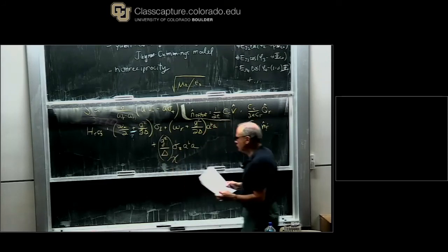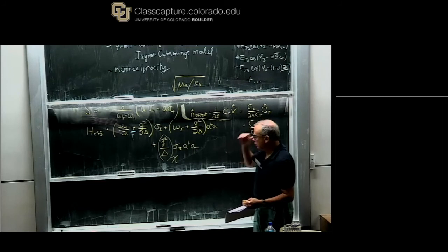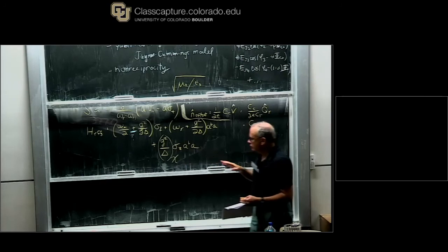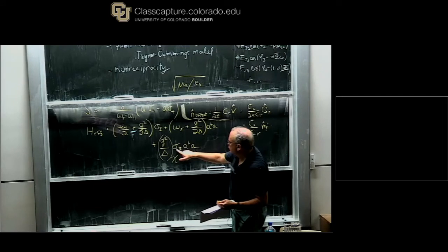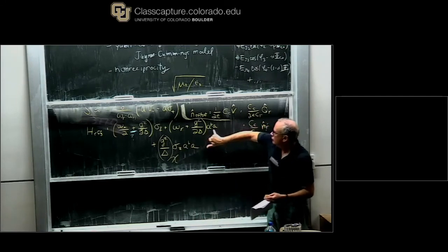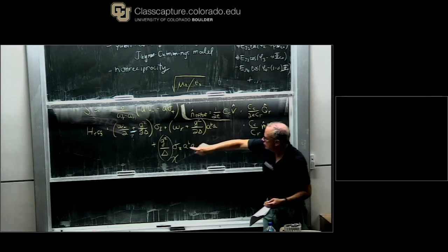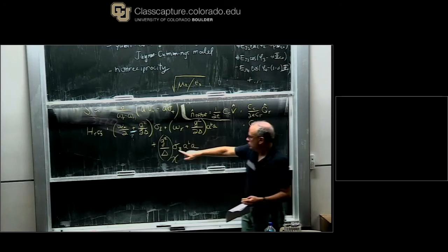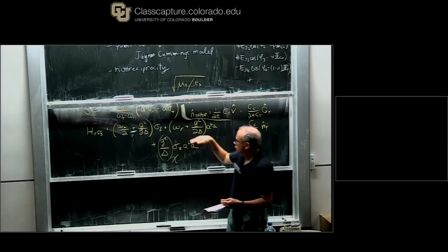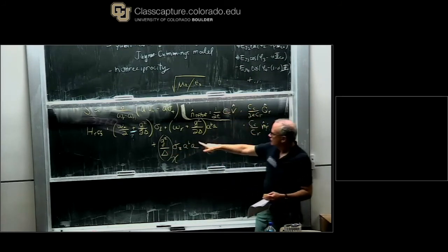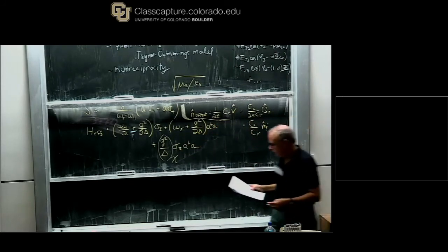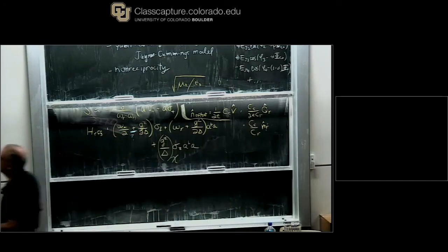So this is the dispersive shift, and it can be read in several different ways, but the useful way to read it, because it leads immediately to how you measure this qubit, is that it's an additional shift of the resonator frequency which is qubit state dependent. If the qubit is a 1, it shifts the frequency up a bit, and if the qubit is a 0, it shifts it down a little bit. And this in fact provides the basis for how to measure this,